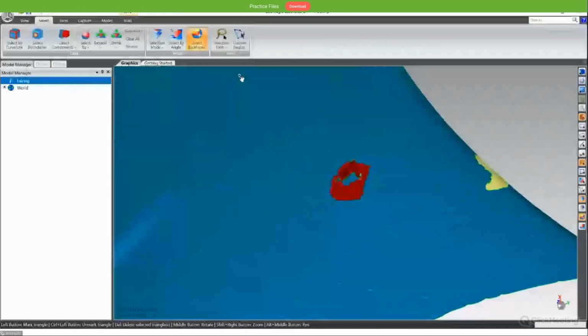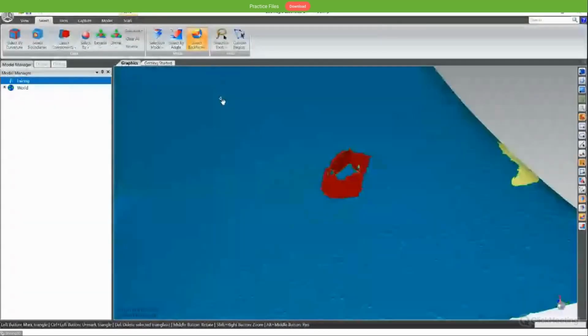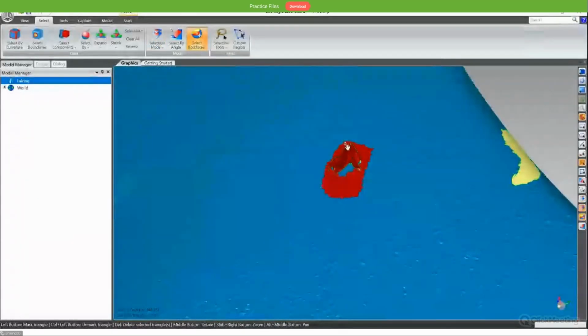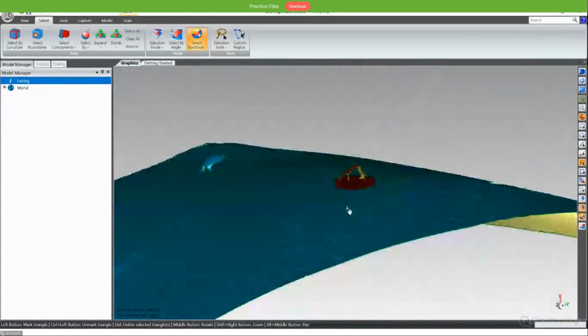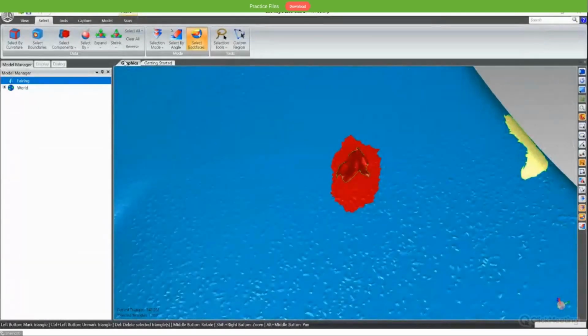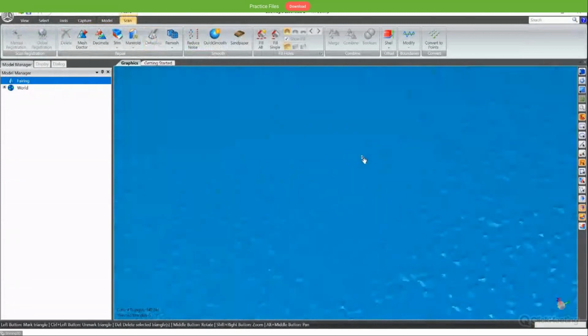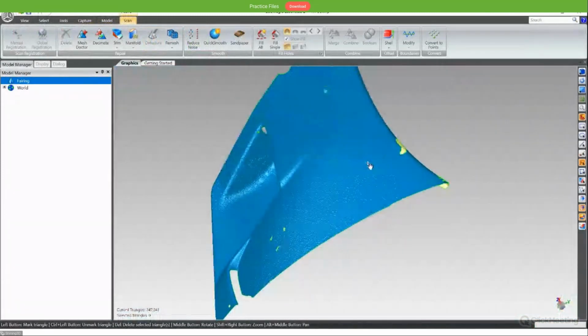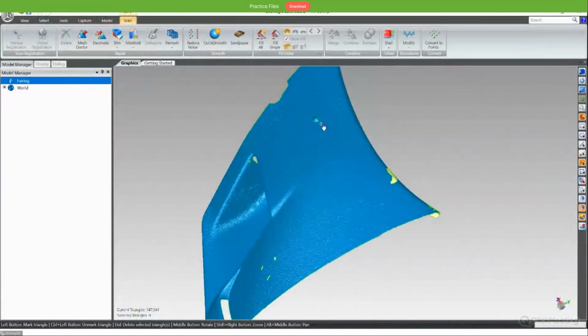So in this situation, we should choose the selection mode, the select through function, and then select this area. The difference is all the parts of this area have been selected, and then you run the defeature like this. Okay. So that is not a floating part.